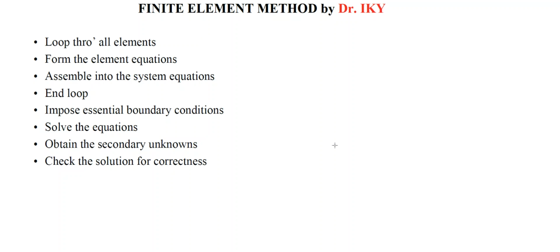And maybe I should add a little bit about the theoretical notes. We have got an element stiffness matrix K. How is the K, if you remember? K is symmetric, but the rank of the matrix is deficient. That is important. Symmetric and rank deficient. For the structural stiffness matrix, global K, I'm talking about global K, it is also symmetric. And the global stiffness matrix K is rank deficient before imposing the essential boundary conditions. And K is positive definite after imposing essential boundary conditions.